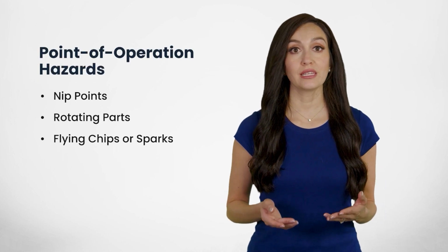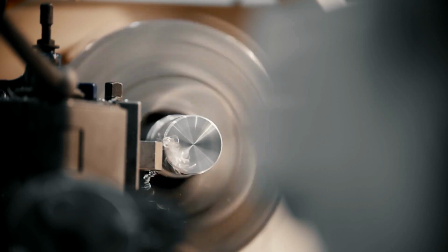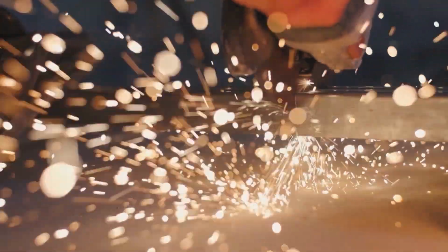On the other end of lockout-tagout is machine guarding. Machine guarding involves protecting workers from hazards at what is called the point of operation. These hazards can include nip points, rotating parts, and flying chips or sparks. Think about the tools and equipment you work with or around. Are you at risk of amputations, pinch points, having loose clothing pulled into moving parts, or exposure to flying materials or sparks?